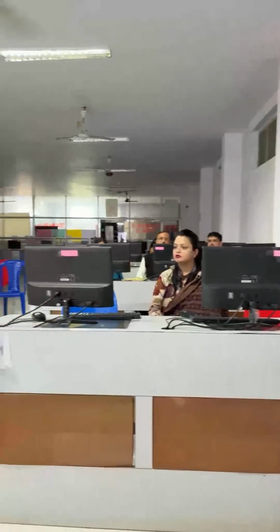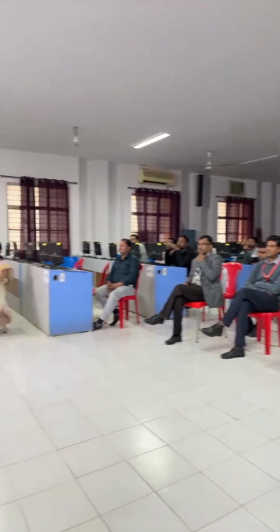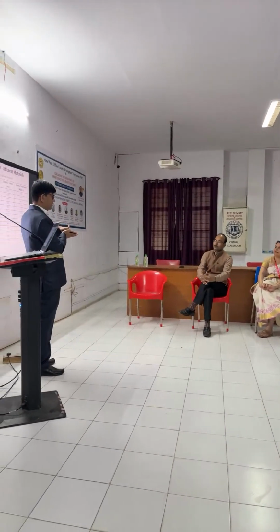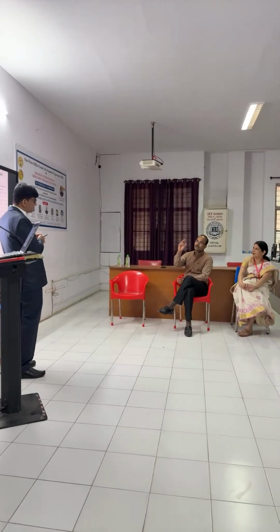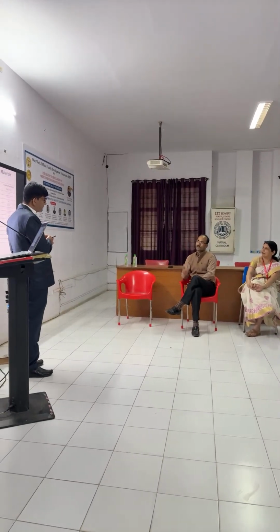Because the velocity is fixed for that particular material, you can't control that. What you can control here is thickness. And thickness is in your hand, because you are going to deposit that particular layer. Yes, it is in your hand, how you have to deposit. Because see, first QCM, quartz crystal microbalance, in that we do not have a controllable thickness because our substrate size is fixed. If the thickness increases, then the frequency is also affected.